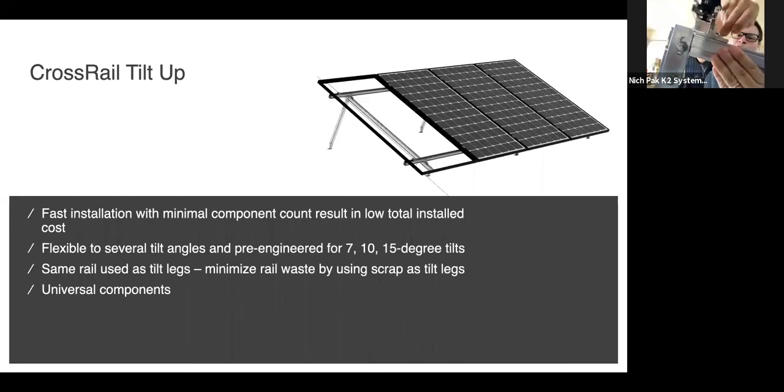And then we use a bolt to engage into the channel of the rail down below. So it mounts into the bottom channel, and then it grabs onto the T-track. So no T-bolts and L-feet needed on this portion right here, because you can use this climber. You also have an adjustment downslope and upslope of the rail. So I hope you guys can see this pretty clearly.